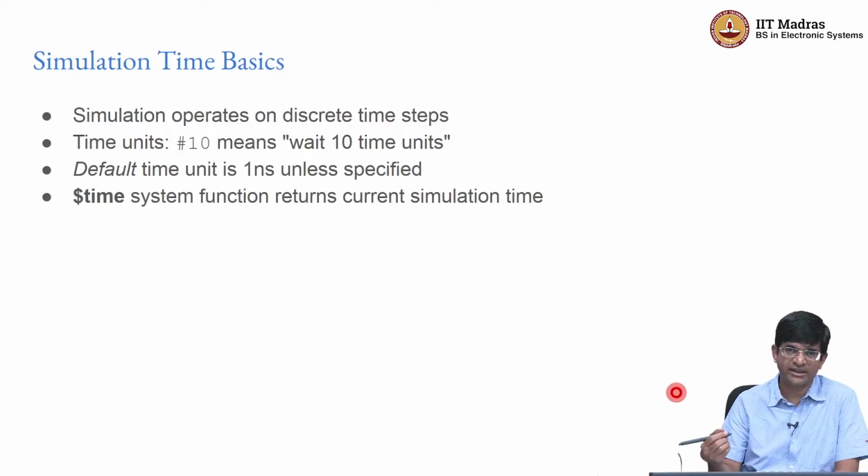I mean, yes, we think in terms of minutes and seconds, but you can go further down. You can go to milliseconds, nanoseconds. Even that's not the end, right? There is always something finer than that. But as far as Verilog simulations are concerned, at some point you have a granularity, and there is a time step that says I don't treat any smaller level of granularity than this.